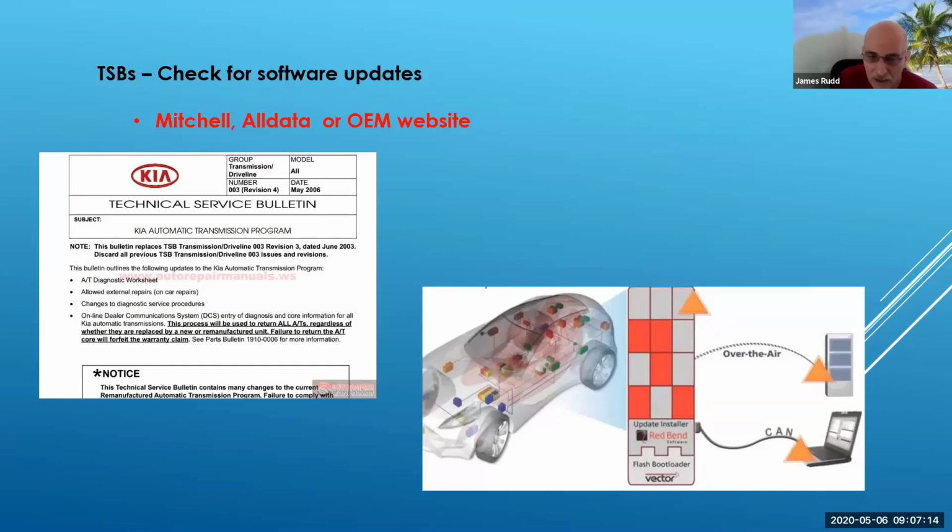The reason I have an issue with dyes in air conditioning is that it displaces volume, and I'm not really so much worried about that in the oil. If I have a leak I can't find, I use a dye as far as oils go. And if there's an evaporative leak, sometimes that's the only way you can actually find it. But anyways, I went ahead and I smoked and I smoked and I smoked.